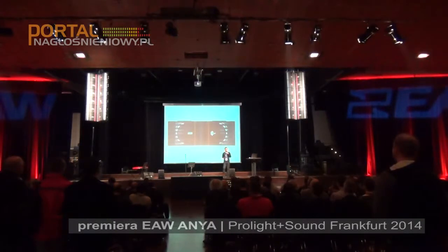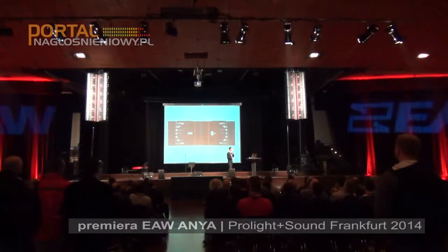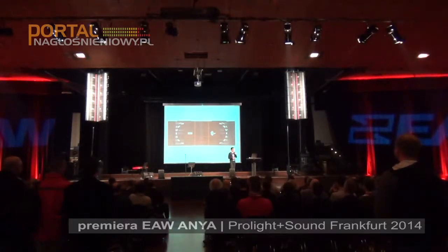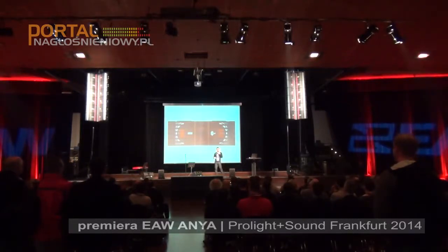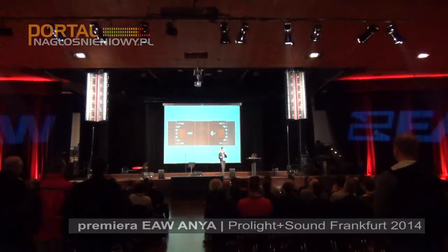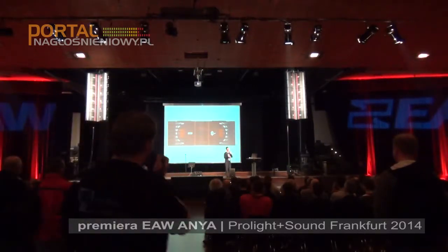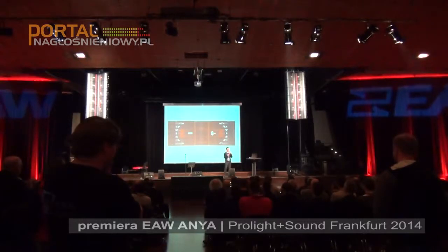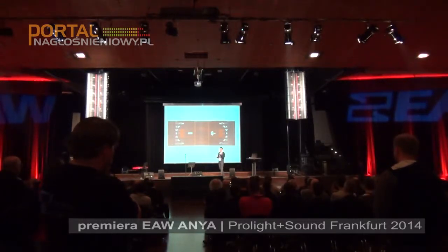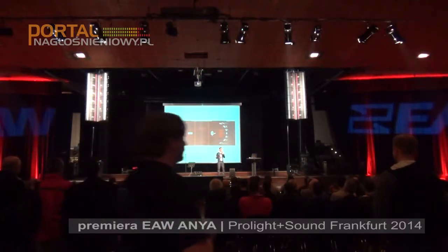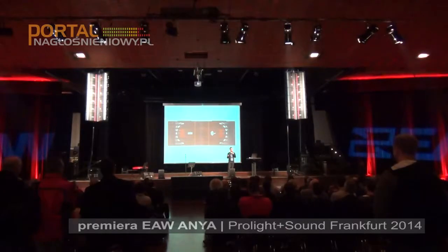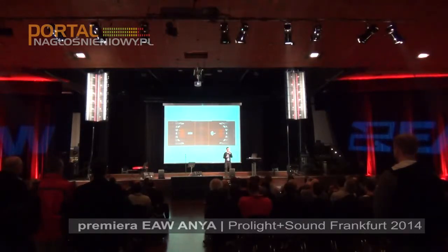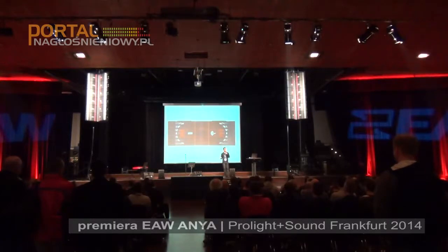Of course, we couldn't pay attention to just the vertical, right? Because we knew that we also wanted to modify and control the coverage horizontally. So, as we've done with many EAW systems, KF730, KF740, we use unique techniques, in this case, strategic placement and size and positioning of the apertures and the ports tied to the low frequency devices to ensure that the natural horizontal pattern control that we achieve from that low frequency section naturally matches the 70-degree pattern that we had already defined for the mid and high frequency section.